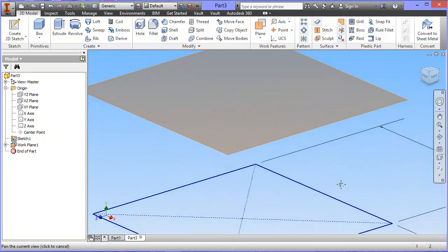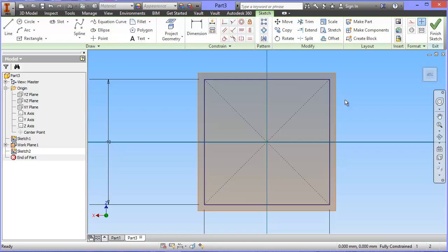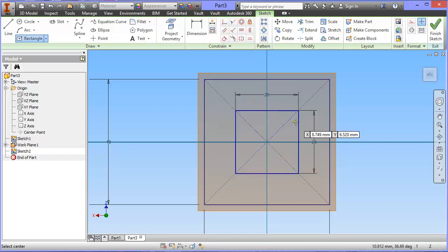Let's drag that down so we can see it, and even zoom a bit smaller. So it's floating in midair. There's nothing on it. What I want to do is add a drawing to it. So if I click on it on the edge, I can go to this one that says create a sketch. I'm going to hit sketch, and now I've got something to draw on. On this one I'm going to draw another rectangle, still with a center point. I'm going to click on here, come out. This time I'm going to make it maybe 20, hit Tab, and 20 and hit return. So I've got another one there which is 20 millimeters.